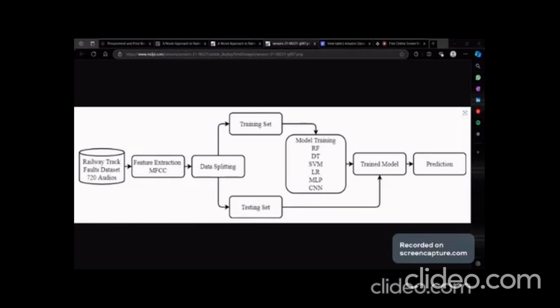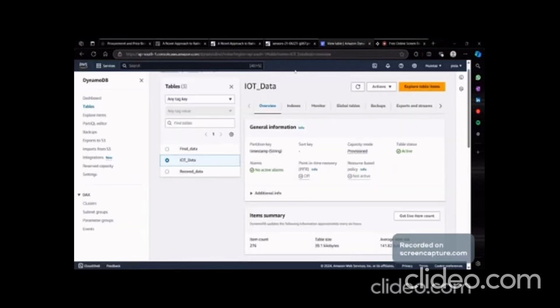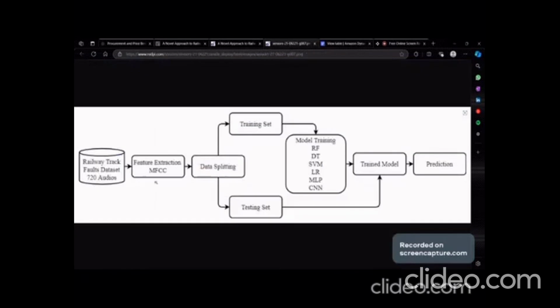Our system captures audio recordings clipped into 5-second intervals and stores them locally. When the train halts at a station, the stored files are uploaded to the database in base64 format to optimize space. The model retrieves these files, extracts MEL frequency, and applies fast Fourier transform to derive 14 key audio features, and simultaneously processes audio from the auxiliary mic to perform noise cancellation. This noise reduction is critical for enhancing anomaly detection, as background interference can significantly reduce the model's efficiency.